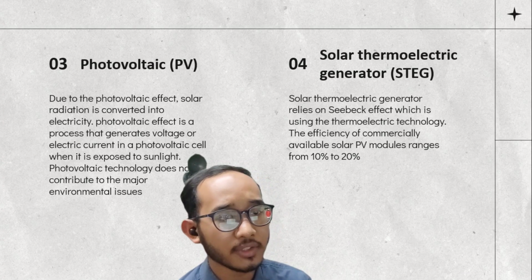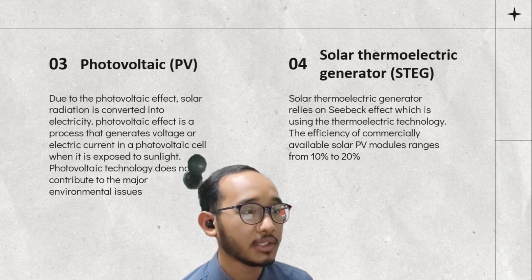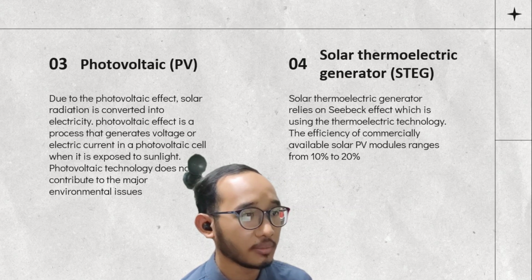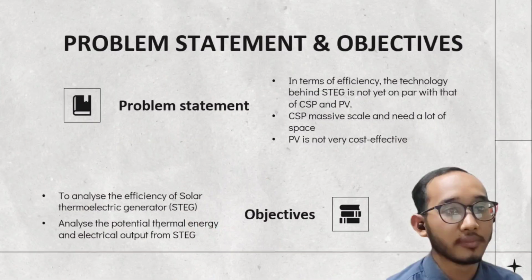STEG system efficiency depends on the optical and thermal efficiency of the collector, the ZT value of the thermoelectric modules, and the efficiency of the cooling method.